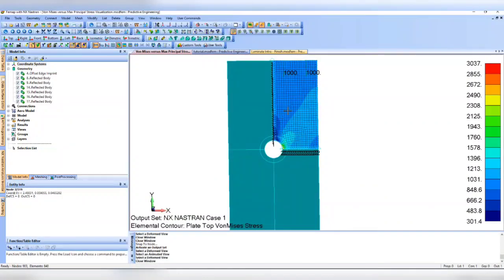when you're modeling very complex systems, if there's a way to do it faster, do it faster. And if your system is symmetric, only model either half or a quarter of your system so that you don't need to waste time with meshing with higher element counts, higher node counts, and higher processing times.